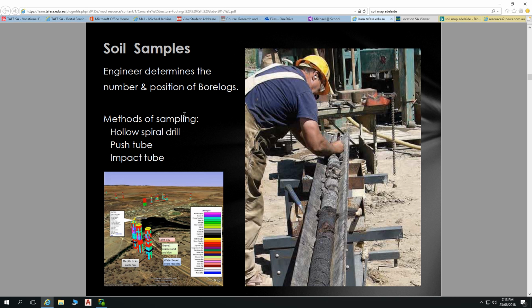We've got your site plan and your borehole locations. Those boreholes typically marked like that. BH1, BH2, BH3, for example. You cluster them, aggregate them where your house is going to be. So let's say our house is going to be here like this. So in a city place, it's taking up the whole block. And then, because it's important to know where those soil samples are being taken, because soil horizons differ through those soil samples, as we'll see in a minute.